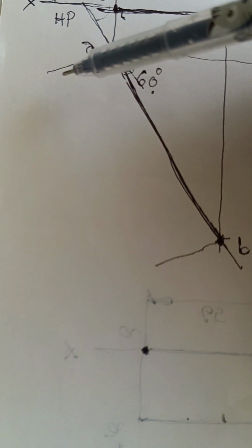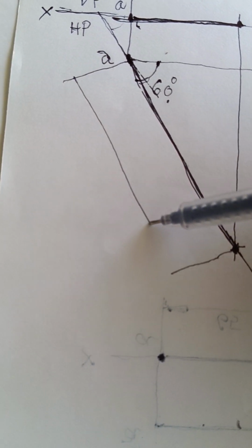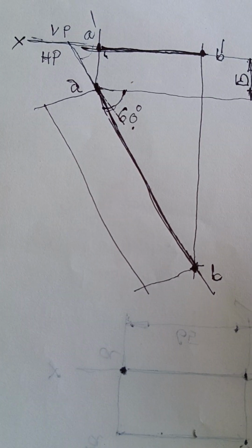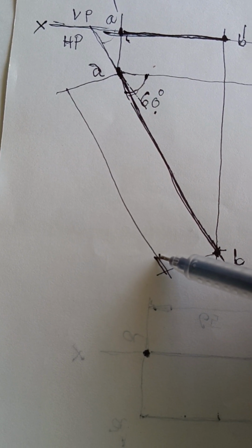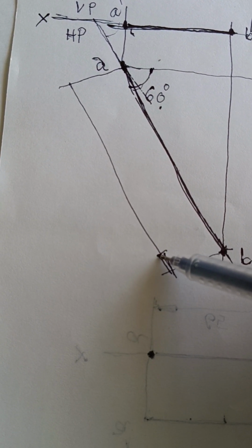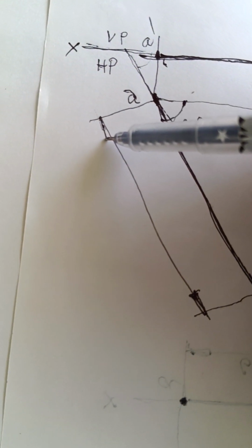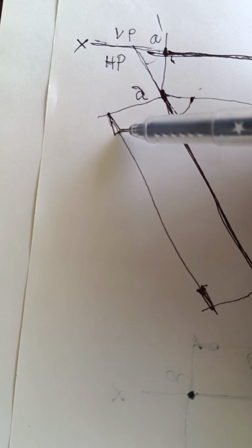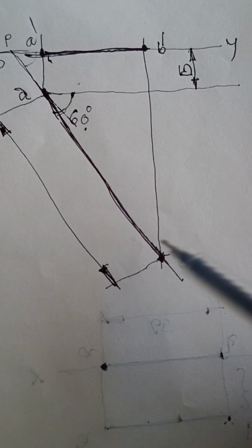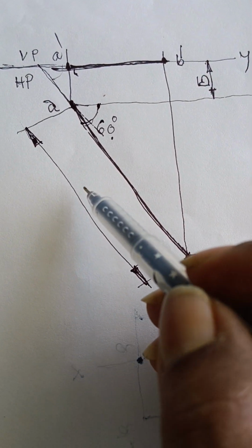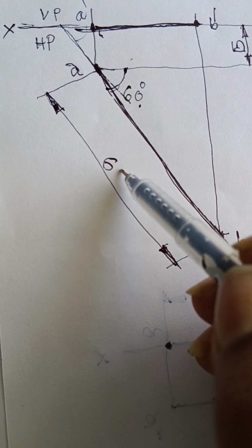In between these two extension lines, draw a light line parallel to the AB top view. At the end of this dimension line you need to give arrow tips, following arrow dimensions of 1:3 or 2:6. After drawing the dimension line in this fashion, you have to give the dimension value exactly at the mid of this dimension line.